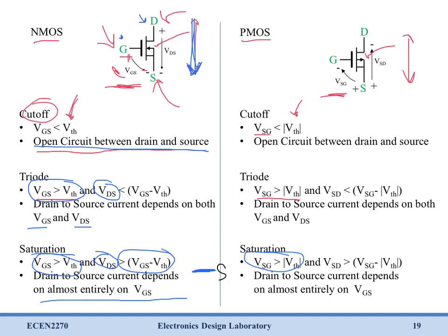If we say this is our source voltage here, then we have our gate at some voltage which is slightly above our source, so the distance between these two voltages is greater than a threshold. And then our drain is at some voltage greater than both of these. So our drain is higher than our gate, and our gate is higher than our source. So this works, and this lets us operate in saturation, which looks like a closed switch. It means that the current through is only really dependent on VGS. Apply enough VGS and you close the switch and it operates.